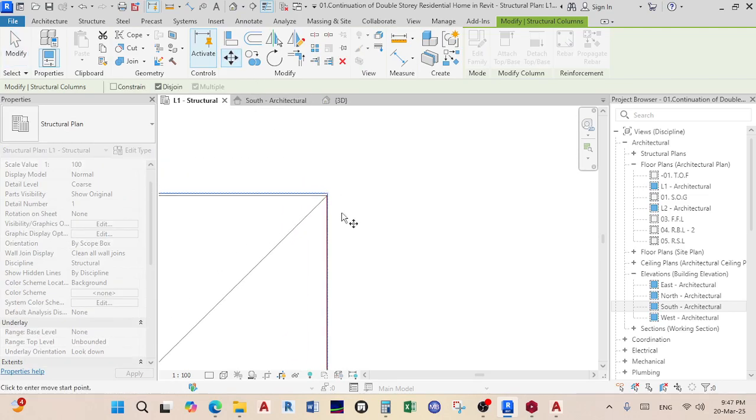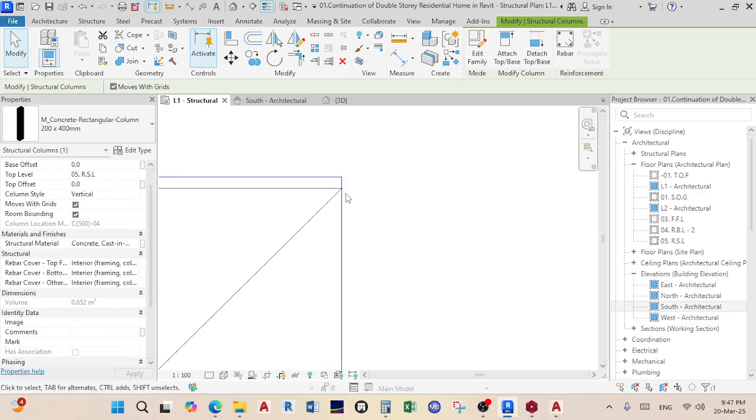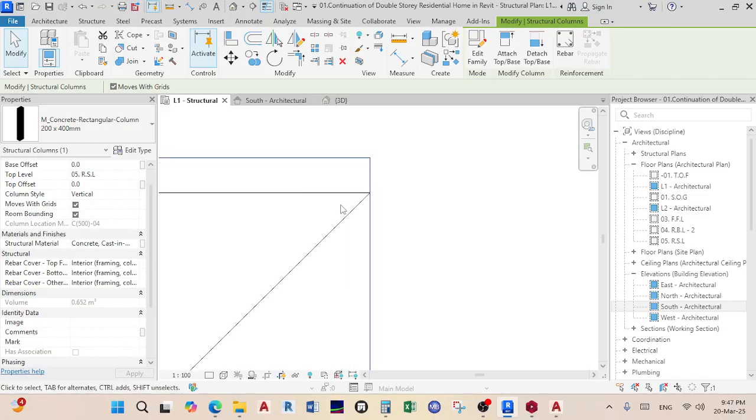Oh, there's also a feature called the align tool. Very important too. What the align tool does is it's a command where you ask the object that you've selected to align to something that's already existing. So for example, for this one that's out, when you select it, it gives you this modify thing, and then the align key is here, the command.